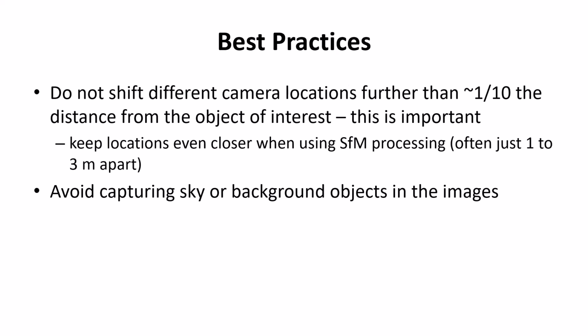Think about it. Your eyes are only a handful of centimeters apart, and you can do a pretty good job of seeing distance and stereo. The photogrammetry will do okay. If your cameras are really close together, it'll do fine, except that your depth accuracy will be somewhat diminished. So often for things that I'm involved in, just something the size of a house or a building, I may be just 3 meters apart for each camera station, and I may have 5 or 10 or 20 camera stations. I just walk along, take a picture, walk along, take a picture.